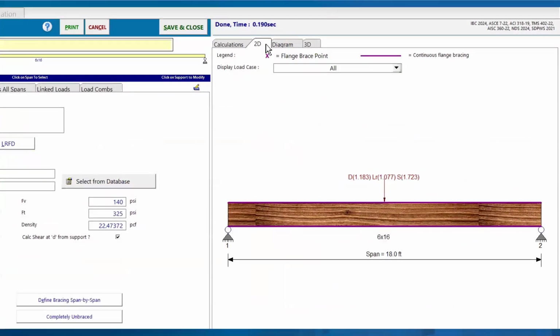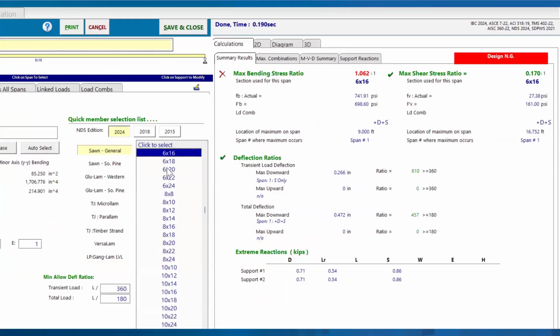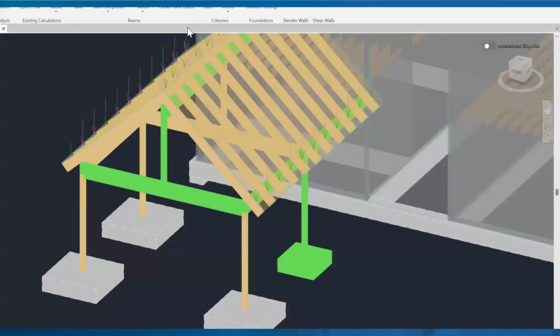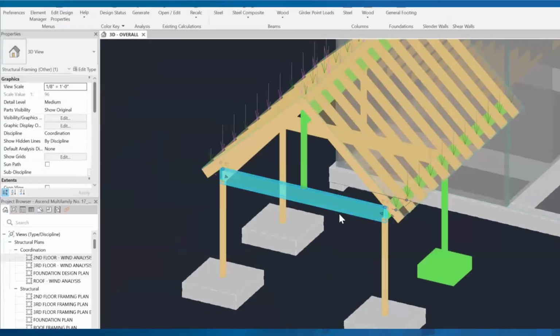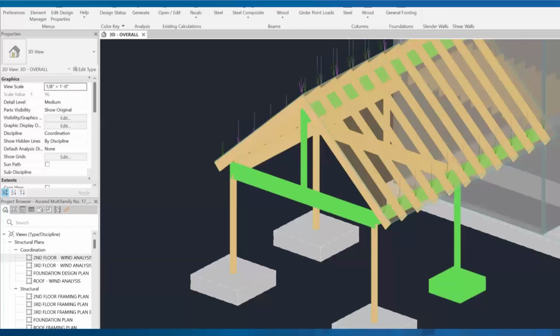So now we can see the axial force in that transfer post is seamlessly transferred as a vertical applied load at the middle of our transfer girder on the front face of the building. We can actually toggle the size of that girder if we need to. In this case, we're going to 6x18 timber. And that size change will happen automatically when we save and close. And again, we have that green status highlighting that tells us, are we passing? Are we failing? What's our overall engineering capacity status?